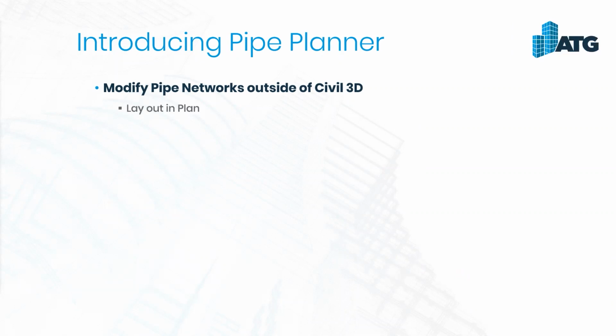But in order to do that, we need to do a couple of things. Number one, we have to lay these out using the pipe network toolset in plan view. So yes, we can change inverts using this tool. We can change the sump depth, but we need to have the X and the Y coordinates figured out at least for that.